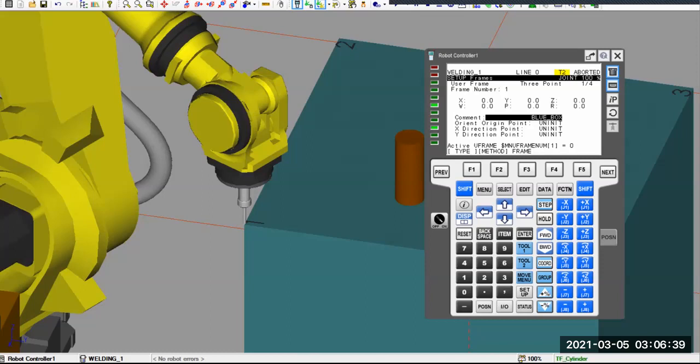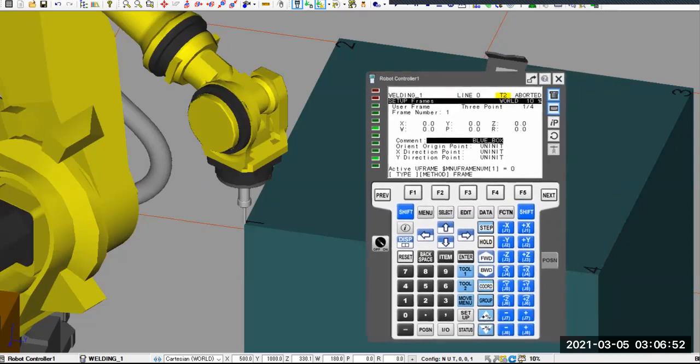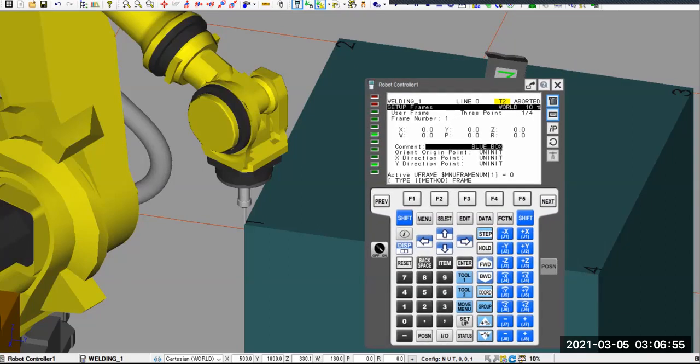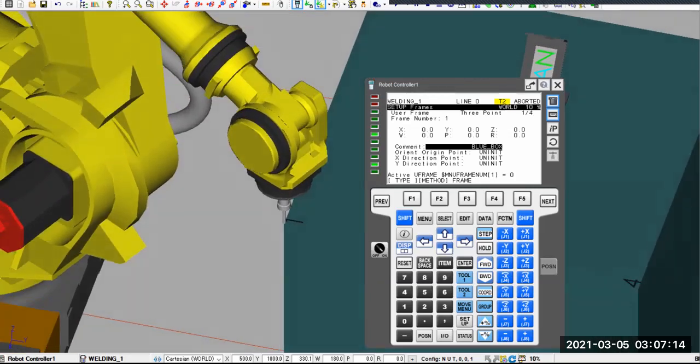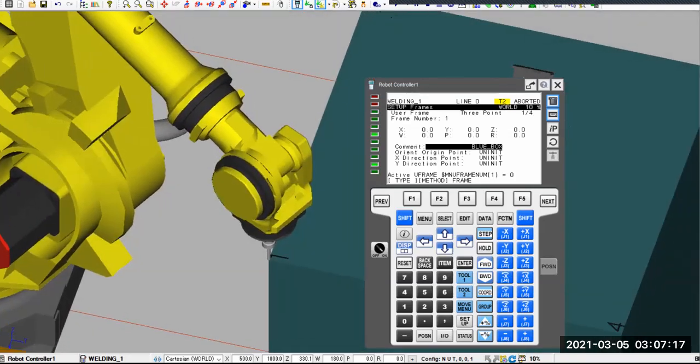So remember before we talked about how we can jog the robot in world coordinate. Right now it's in joint. I want to change to world. So I can change to world. And if I ask you, we have 4 different corners on the blue box, right? So for example, if we want to move the robot TCP from corner number 1 to corner number 4, we are in world, so just go along this edge on the box. What choice should you make by the right hand rule, if you remember it, right?